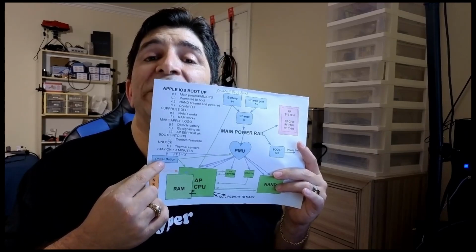That is 1.8 volts. So if I were to go into my phone and find the power connector, where the power connector connects, there should be 1.8 volts present. You can go in there and test it, and you can find 1.8 volts. Now, what happens when we actually push that button?